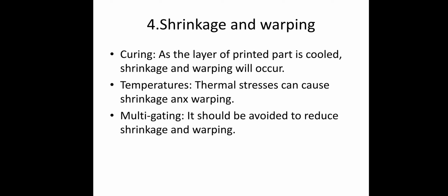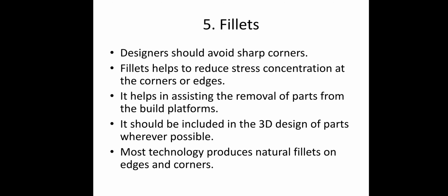Then the fourth one, shrinkage and warping. Curing: as a layer of the printed part cools, shrinkage and warping will occur. So sufficient allowance should be provided for curing. Temperatures also play an important role in the shrinkage and warping of printed parts, so temperatures should be controlled. Multi-gating is a problem and should be avoided to reduce shrinkage and warping.